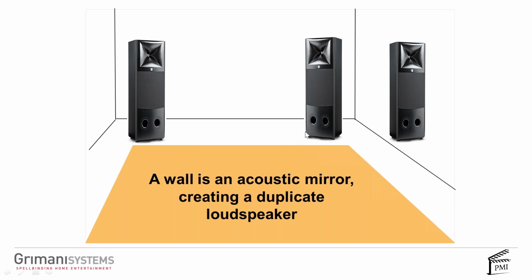By the way, all these diagrams are from Floyd Toole, and this is a very well-designed loudspeaker in the JBL line, made mainly for professional applications. Well-designed means it's a good broadband speaker with good frequency response, but it also has this funky thing up here that looks like a sideways cross. This is a waveguide, with a 2-way compression driver in it. The role of this waveguide is to disperse the sound horizontally and vertically so that it's very constant with frequency. What that means is that the sound that bounces off the walls is a complete replica of the direct sound, which is actually good.